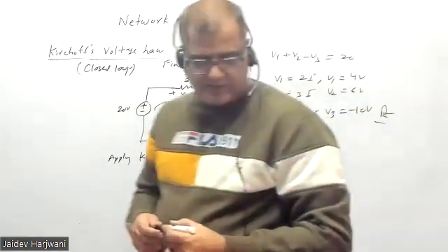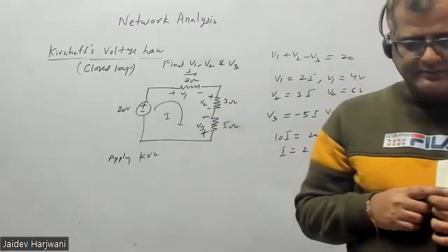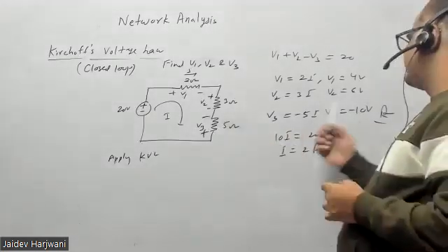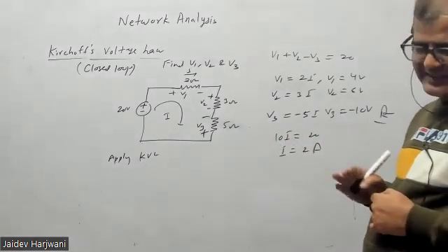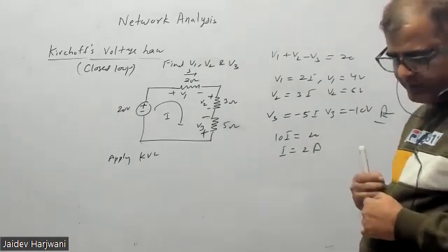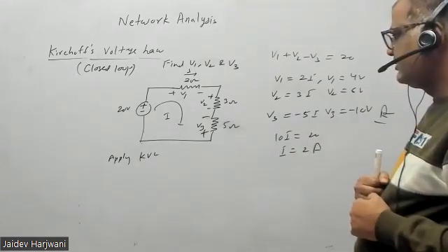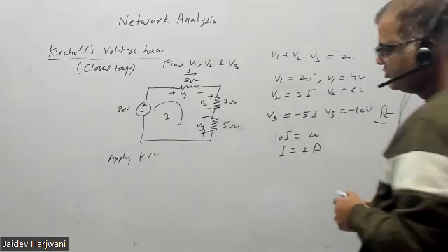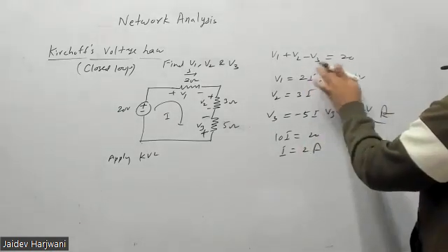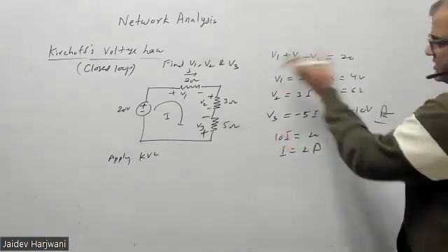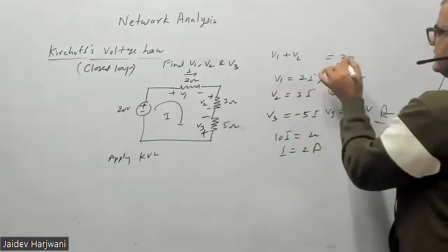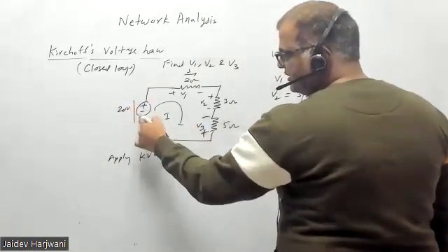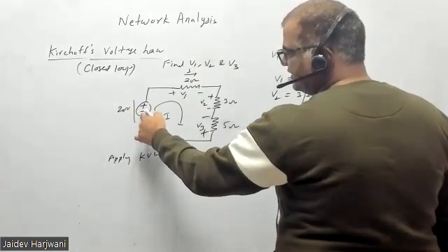So that thing you have to keep. Yes, tell me. Sir, isn't V3 a voltage rise? Voltage rise is equal to minus, so when voltage rise is negative, it becomes a voltage drop. Sir, we can take the voltage rise to one side of the equation. Yes, 20 plus V3, that you can also do. You can keep 20 plus V3 on one side, and the thing is the same. Then minus and minus will be plus. So you have to always take voltage rise with sign.